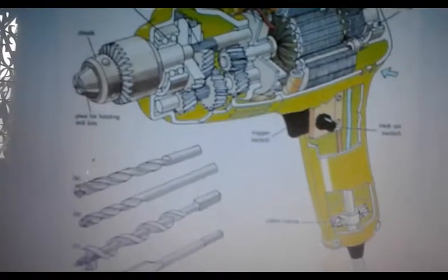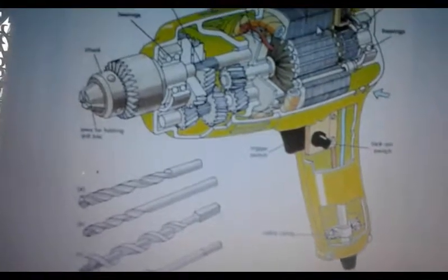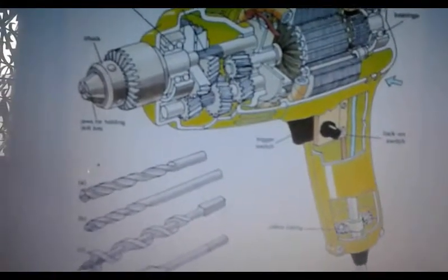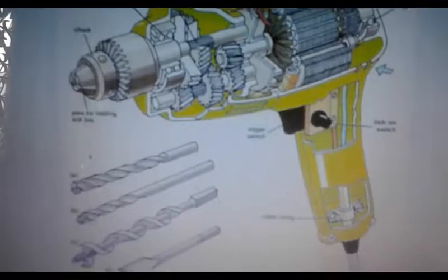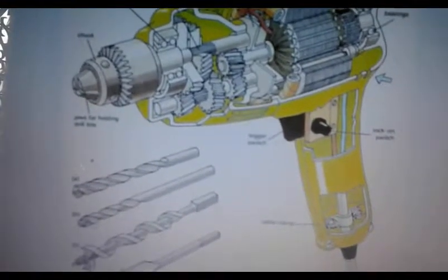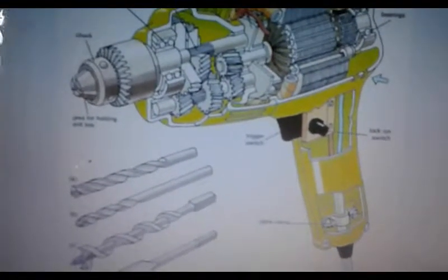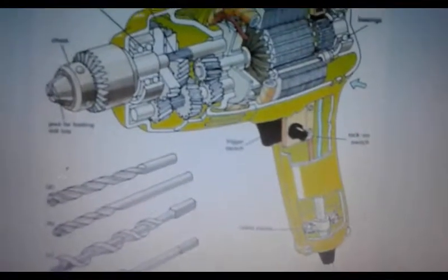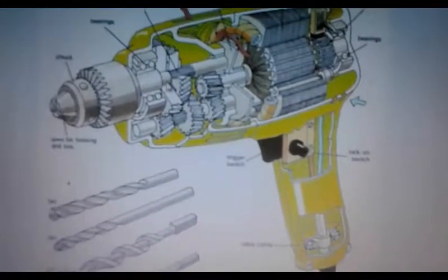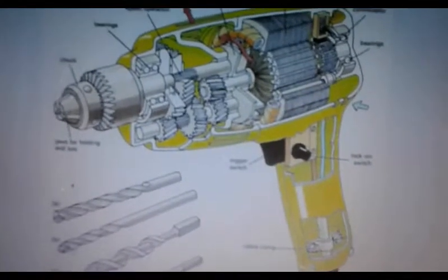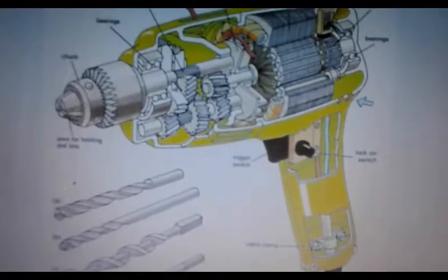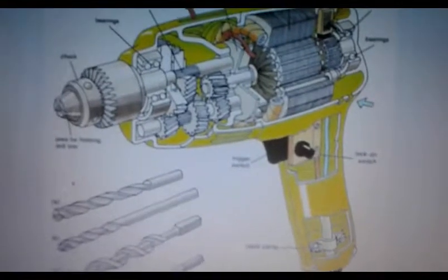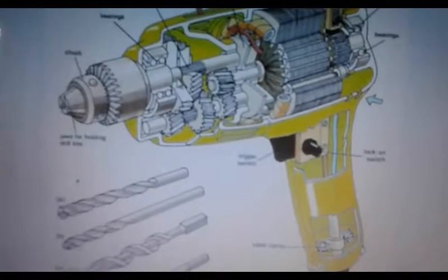And similarly, if we want to increase the turning force or torque that the motor can create, there are three ways: either we can have a more powerful permanent magnet, or we can increase the electric current flowing through the wire. If we increase the electric current flowing through the wire based on the capacity, we can increase the rotating power of a motor. In practice, a motor also will have as many as tens of loops of very thin wire instead of one turn of thick wire.